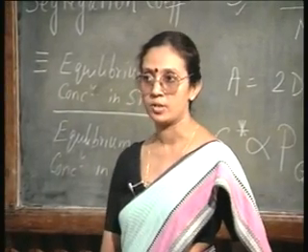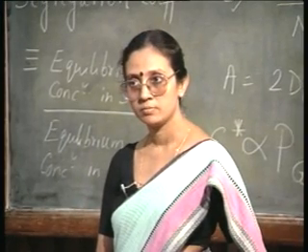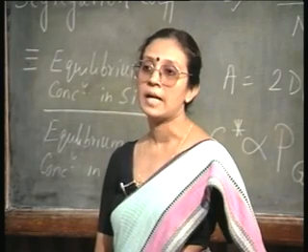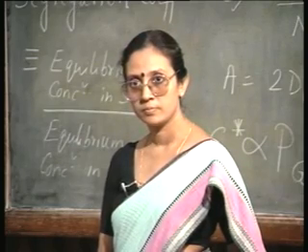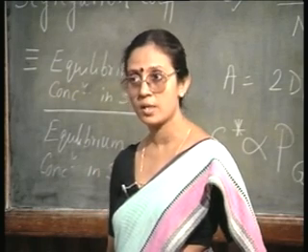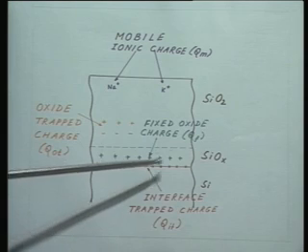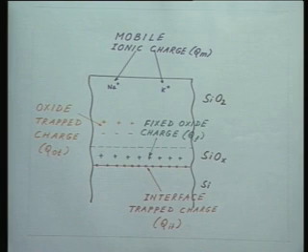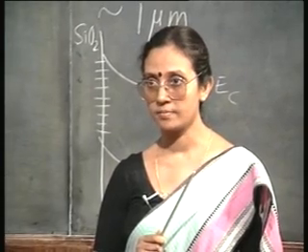Now think of a practical process. Towards the end of the oxidation, you are going to switch off the gas supply. So, chances are that is where the oxidation process is going to be incomplete. You are reducing the oxidant species supply. So, chances are this is where the oxidation is going to be incomplete. That is why here the composition of the oxide will not be exactly SiO2, but it will be SiOx, x being less than 2. I have less oxygen in the silicon dioxide.